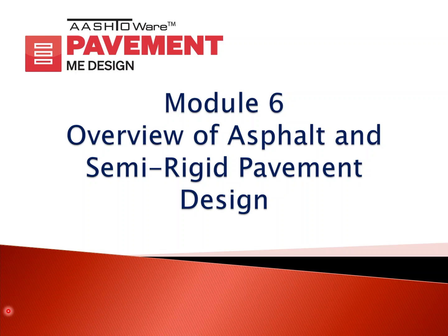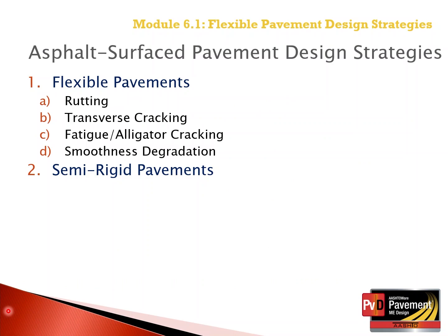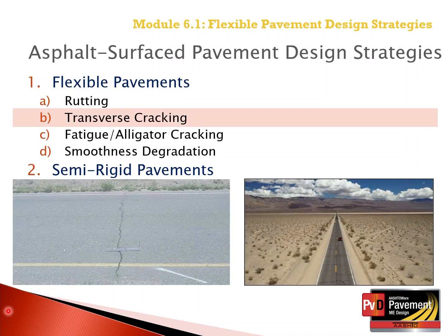Module 6 is on asphalt or flexible pavement and semi-rigid pavement design strategies using the Pavement ME software. We just finished explaining the rut depth models and transfer functions. This session, or Module 6-1-2, will focus on the models and transfer functions used to predict transverse cracks in asphalt wearing surfaces.